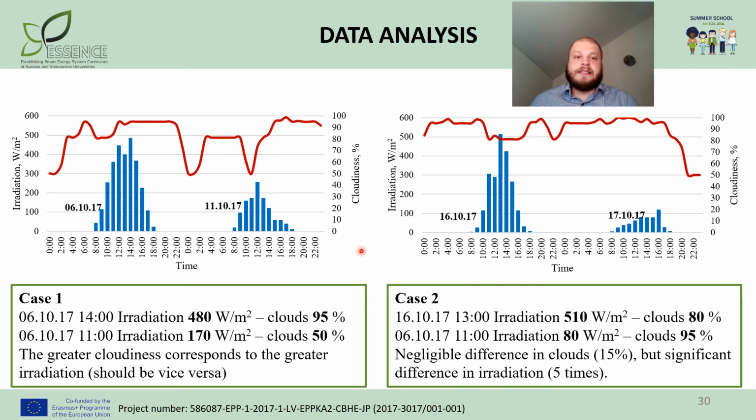When dealing with data analysis of the photovoltaic power plant, I recommend you make a step-by-step, day-by-day analysis of the data associated with the energy production of the PV power plant and the value of clouds, because you will really see that practically the same value of clouds, like it's presented here on the right side of the slide, 90% clouds and 100% clouds, results in a dramatic difference in energy production or in solar irradiation fixed by the horizontally installed pyranometer.